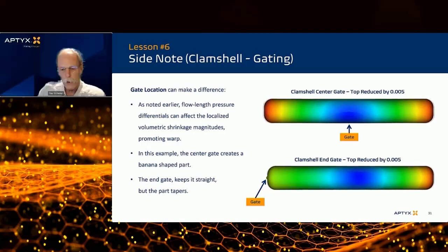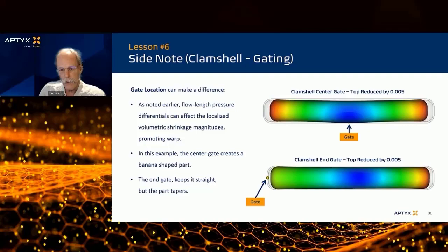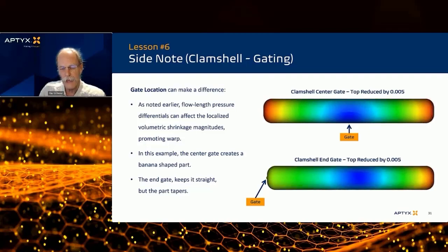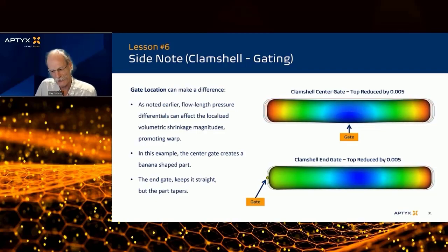Yeah. And then one little side note, never make the mistake of a clamshell of gating one way and gating the other one in another location, because then they definitely won't match up. And you see that happen all the time.